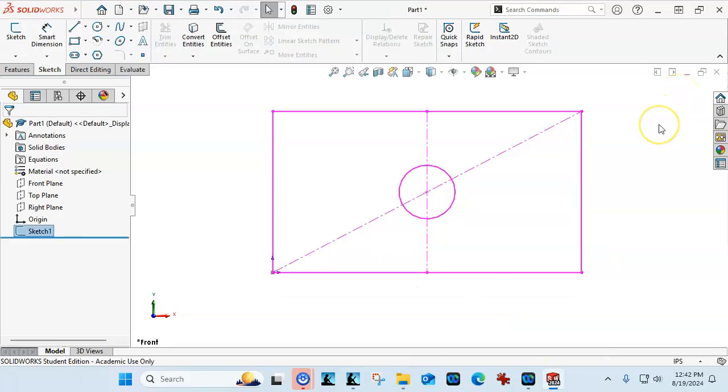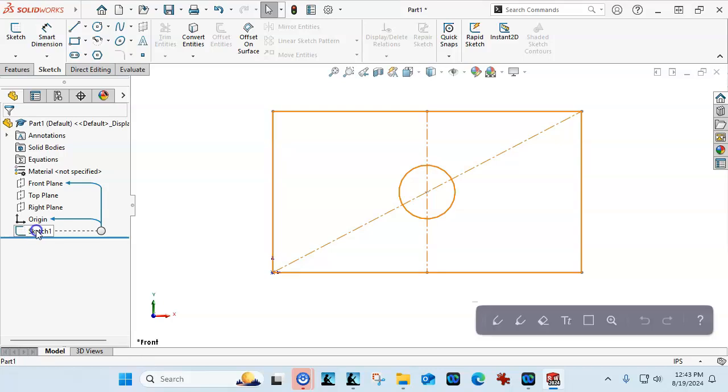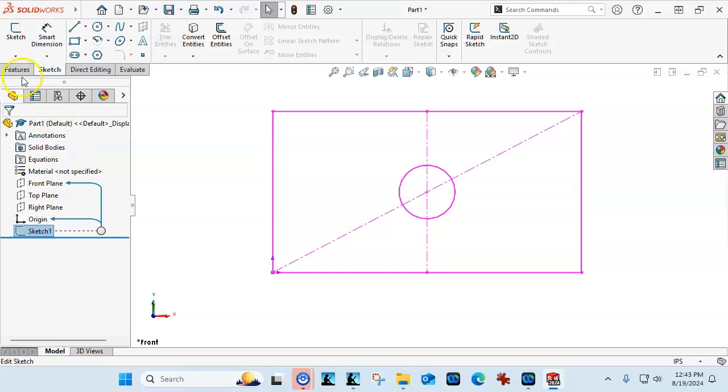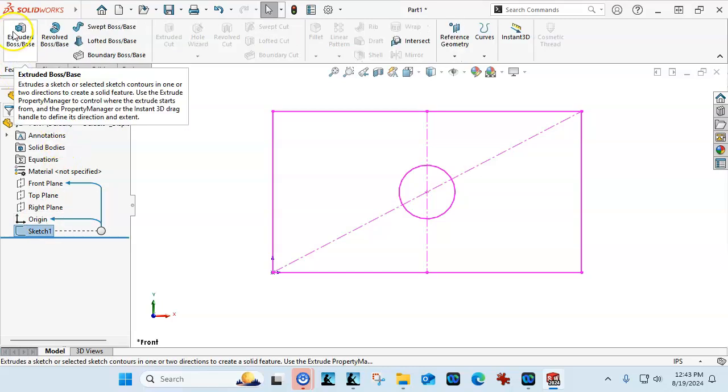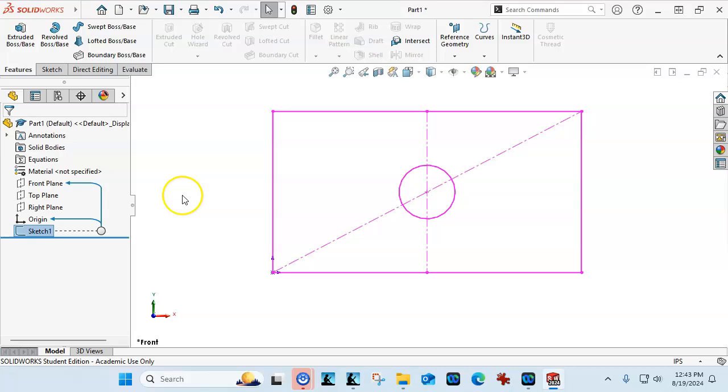Oh, I didn't get to the point of creating the extrusion. So I need to get back into that sketch, or if the sketch is fully defined and complete, I won't see the little minus sign in front, and I have all my geometry, so I could go ahead and highlight and just tell it to extrude.